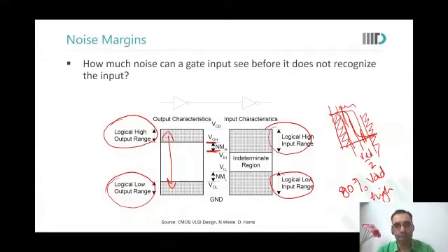So what is the significance of this noise margin? Okay, we were talking about crosstalk. What will crosstalk do? It will generate some small pulses here and there, some glitches here and there. So you do not want your outputs to keep toggling for every little glitch. So that is what this noise margin prevents. It saves power. So noise will now not bother your circuit. Your outputs will not unnecessarily toggle because of noise.